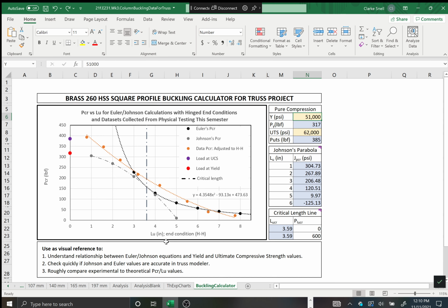And this is some data here, and understanding the idea that if we're measuring data, we can derive an equation from the trend line that's doing the exact same thing. So if we test something in buckling and do a bunch of specimens like we did, we can actually get an equation that does the exact same thing as the theory. Yeah. Johnson is used for columns that are short, not short. It's just that it's between the two, and that's okay.